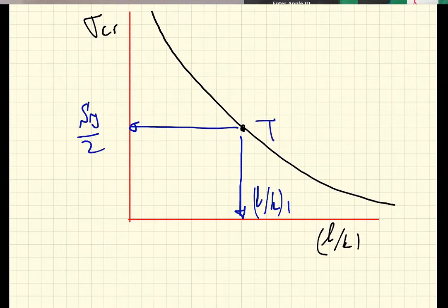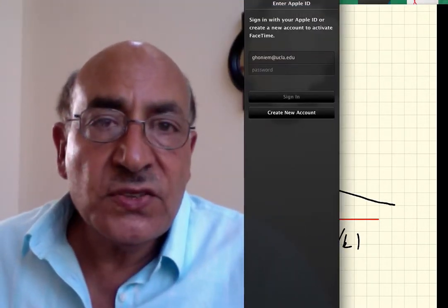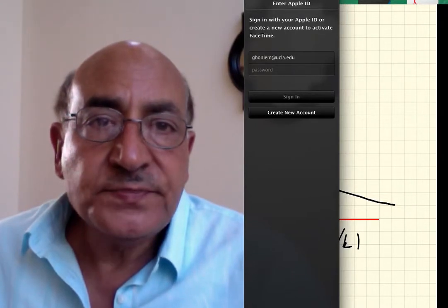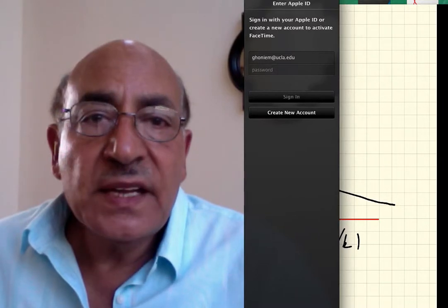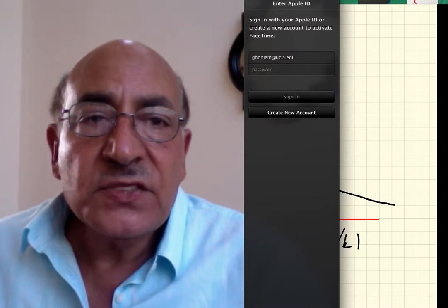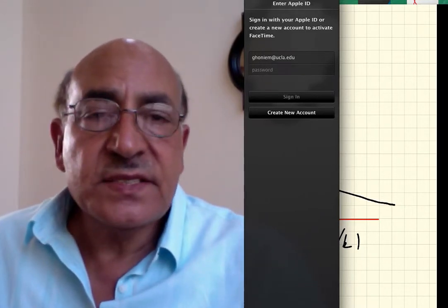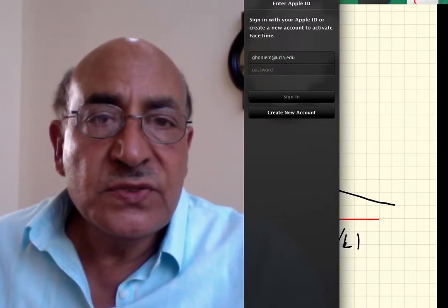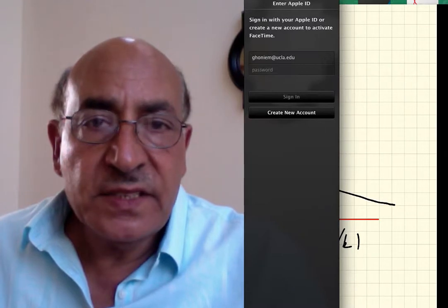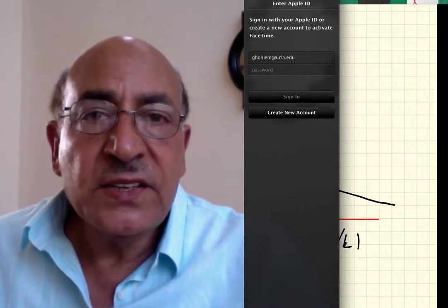Now, as we can see, for a smaller slenderness ratio, if the L over K is really small, then we may actually have a yield condition, and therefore we want to protect against yield rather early. So in this region we introduce another behavior that will govern the design such that we do not allow the critical stress to go anywhere near yield.